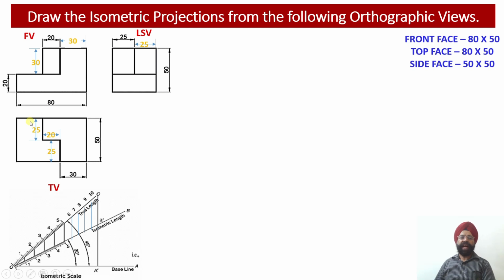So this way I have decoded element number 1, which was this segment over here, and I have decoded the second element, which was the upper portion of this segment. So the upper element is having the shape of a 7. Okay, so this is the shape. So this also I have decoded, that from right corner you move 50 millimeter forward, have edge equal to 25 millimeter parallel to this edge.